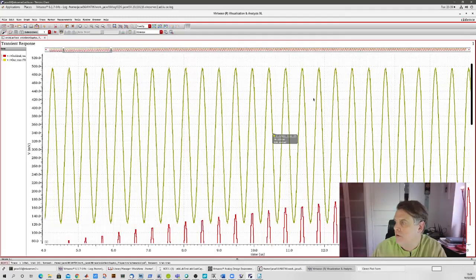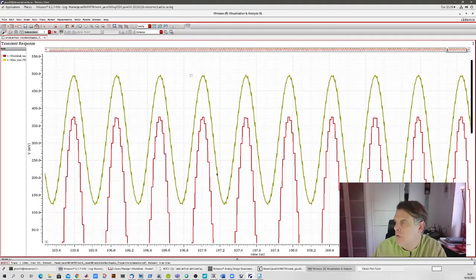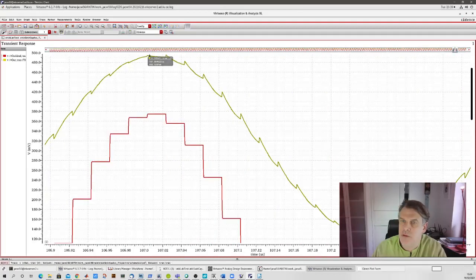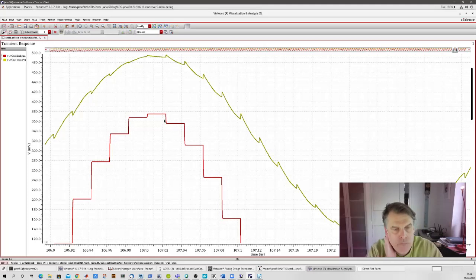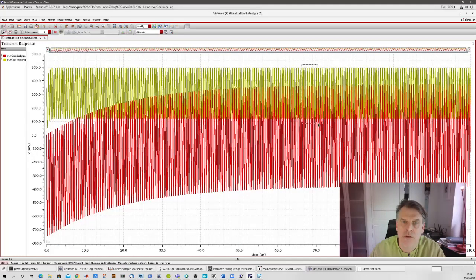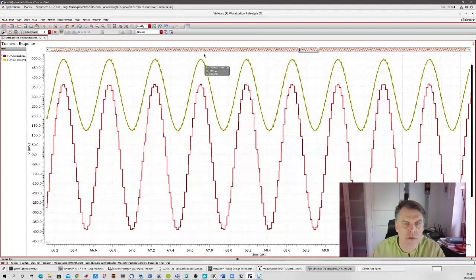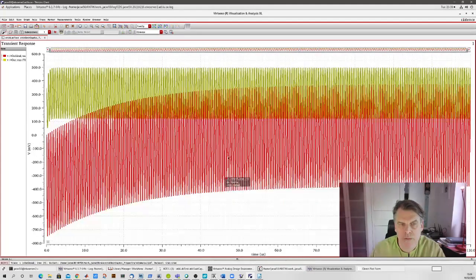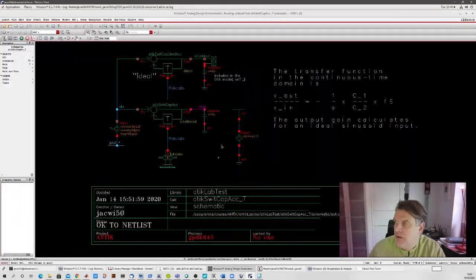We can also take a look at the phases, and here you see they behave quite differently from what you expect on the ideal op amp. There seems to be some glitching behavior happening here. They don't look like square waves. They don't hold the amplitude like you would expect. It doesn't provide you the amplitude you would like. It seems to be half the amplitude, etc. So why is this? What are the factors that limit this? That you have to investigate.